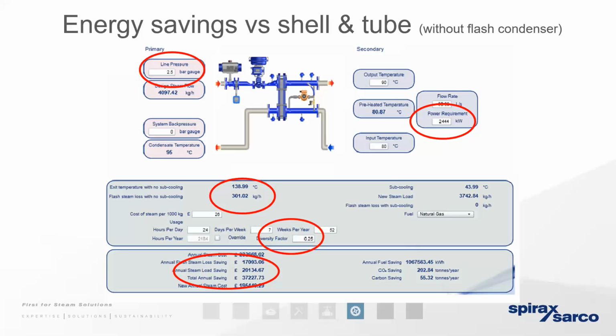Suffice to say that there are a number of key benefits in ensuring that the condensing pressure of steam is held as close to atmospheric as we possibly can. The good news is we can do that by tweaking that area value. If we size the plate pack to ensure that the steam falls in pressure, it will subsequently fall in temperature. We can do that very easily with a plate heat exchanger, but we can't do that easily with a shell and tube heat exchanger. A shell and tube heat exchanger will therefore have a further inefficiency, as that flash steam does need to be vented to atmosphere.